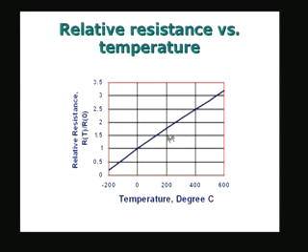So, it increases, and the way I have plotted, if you are not very careful, you will think it is almost like a straight line, but there is some slight nonlinearity. The idea is to see how to characterize this nonlinearity, and how to use the platinum resistance thermometer for measurement of temperature. This is what is going to be the discussion from now onwards.